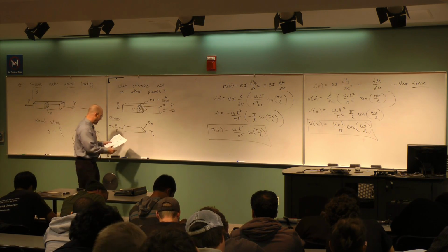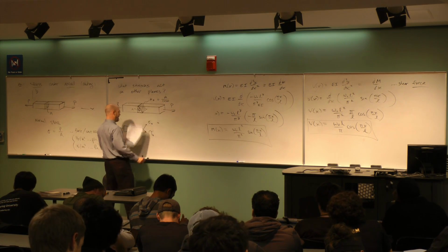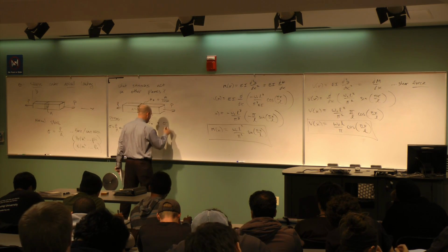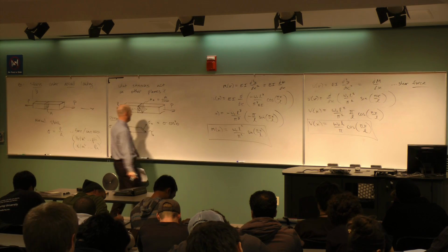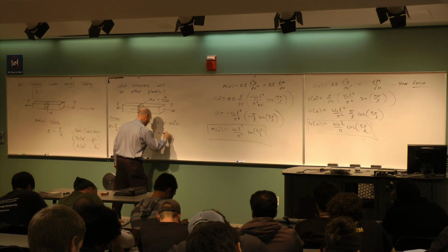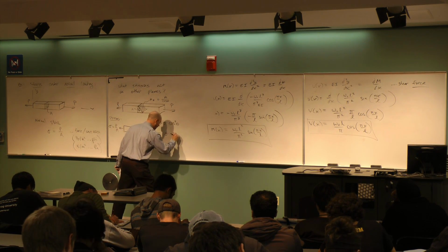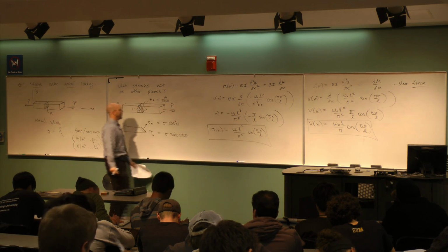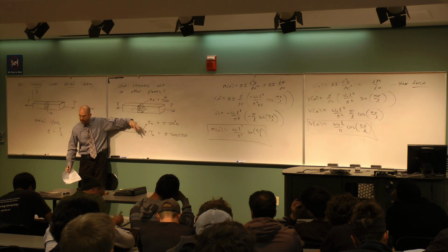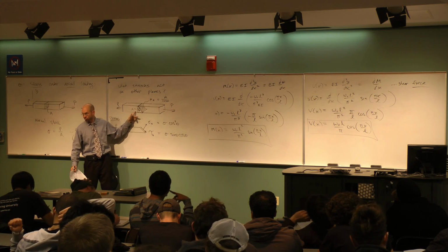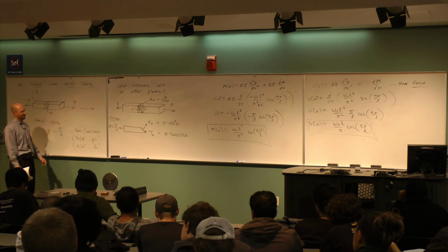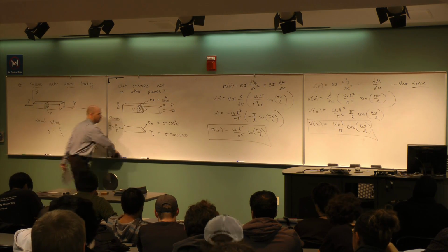Okay, and so here's the bottom line. Turns out sigma theta is the original sigma, this one over here, P over A, times the cosine squared of theta. Okay, the tau theta is the original sigma times the sine of theta times the cosine of theta. And the way you get that is you take the corresponding forces and you divide them by the corresponding area, and of course that area is not the original, right? It's A over cosine theta. So that's how you end up with a cosine squared there and a sine and a cosine there. So this is the background.